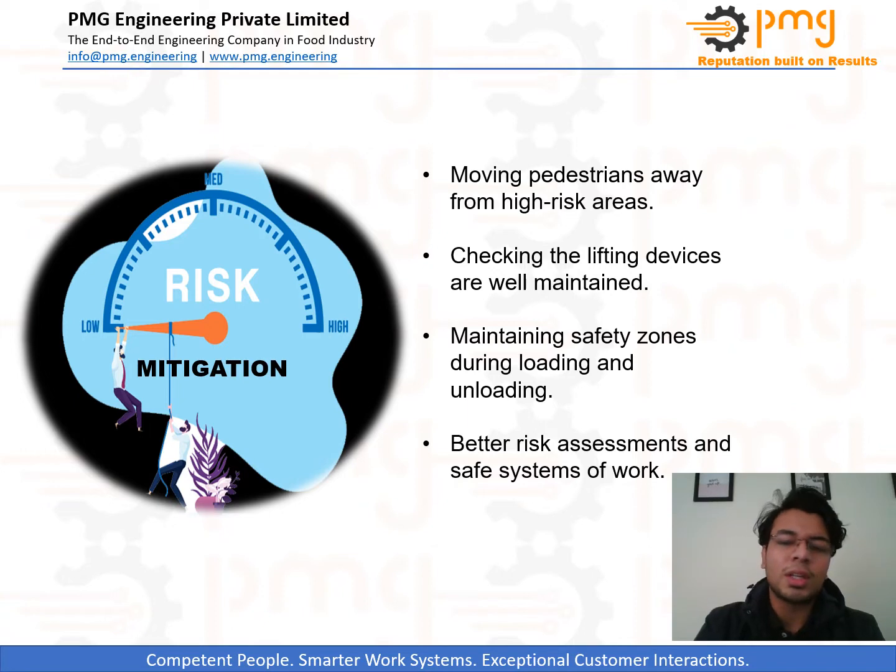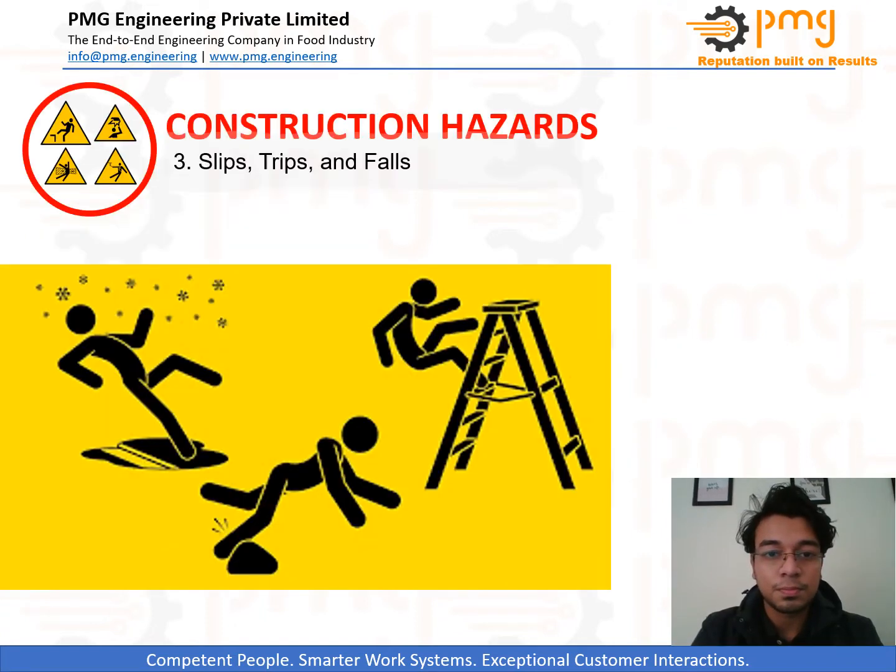We can definitely mitigate those risks. Some ways are: first, moving pedestrians away from high risk areas. Second, checking that lifting devices are well maintained. Third is maintaining safety zones during loading and unloading. And finally, there should be better risk assessment and safe systems of work in place.